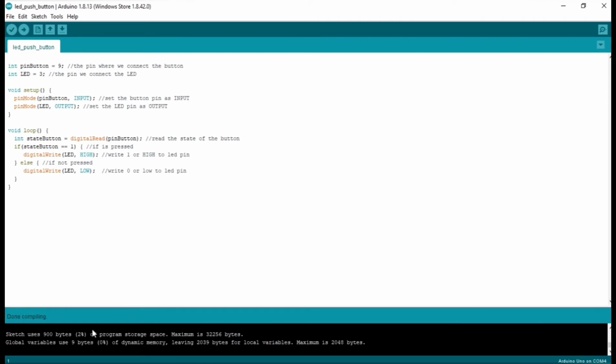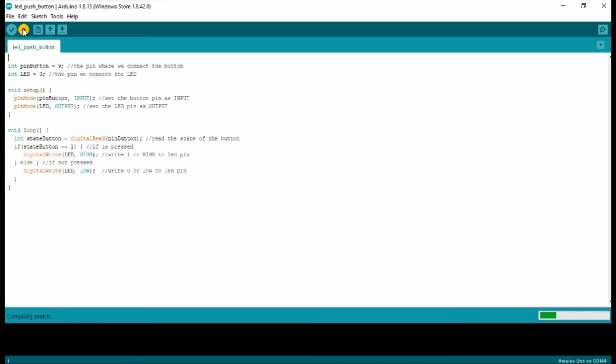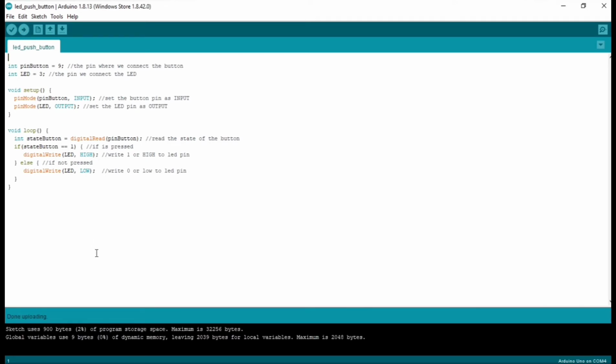Okay, now it's done compiling, and you will see that there is no error. So now let's upload this program to our Arduino. To upload, you need to click this arrow, this one. Okay, now you see it starts uploading. Okay, done uploading. So we have uploaded our program to the Arduino.